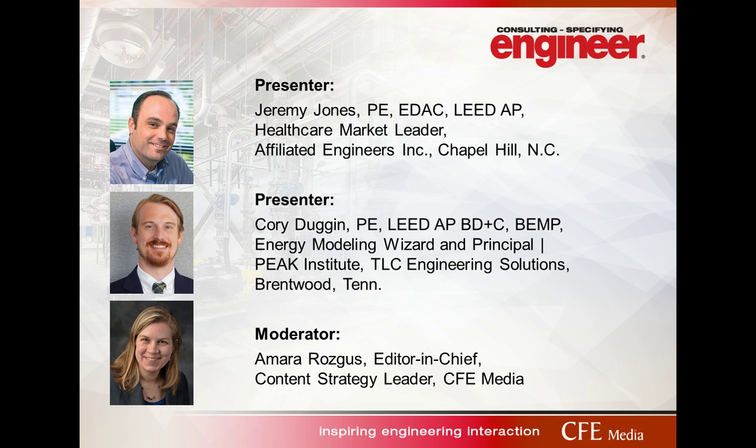You wouldn't be able to do it with a cassette type indoor unit, but you could potentially fit one of their concealed ducted units to try to do that, but you would have a reduction because of the increased static pressure, so there would be a negative effect on the performance from an airflow standpoint on those units. So yes and no. It does make it more difficult. Impossible? I don't think so, but yeah, it significantly discourages it.